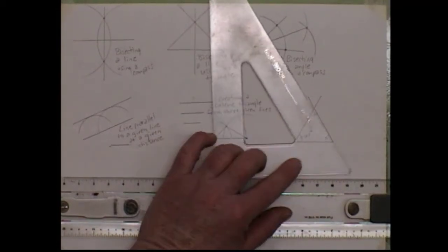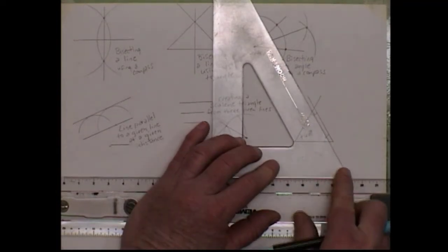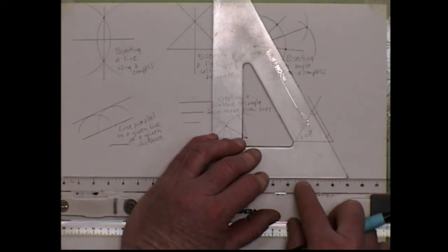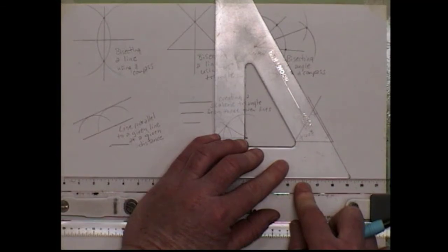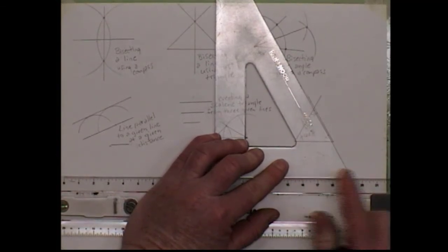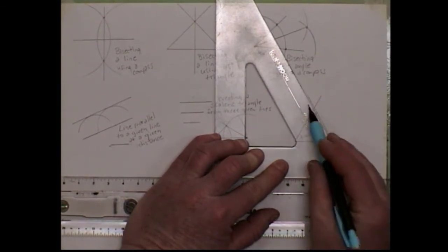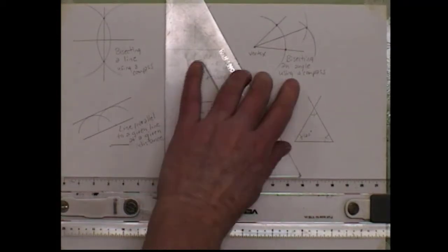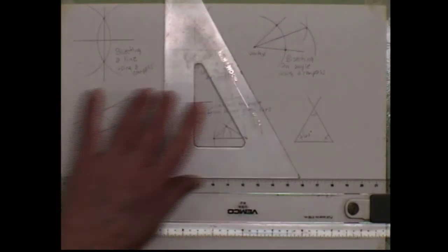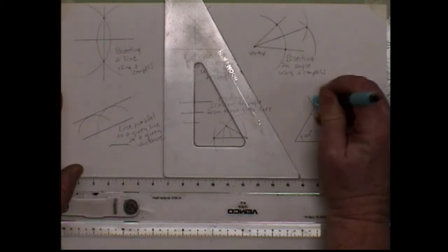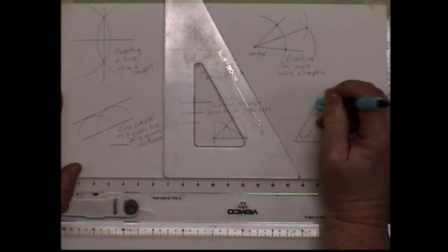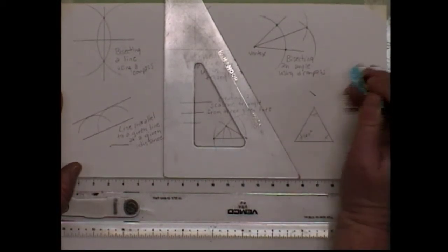So I put my straight edge up using my 60-degree angle, flush with my horizontal straight edge. I put it at that endpoint and made it intersect up here, so I'd have to actually erase those out to get my vertex right there.